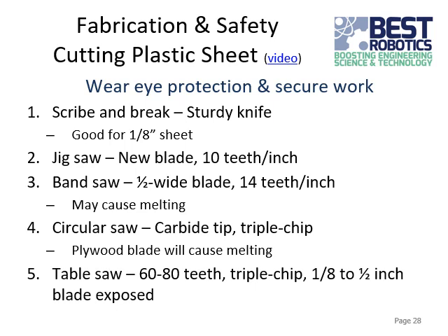Plastic especially can chip or melt and have little bits, like melty bits of plastic fly out while you're cutting it. And all that stuff is really bad, you don't want it in your eyes. So always wear eye protection when you're cutting things or working with power tools or anything like that. And then also make sure that you're securing your work. Don't try to cut something while it's loose and flopping around. Clamp it down to a sturdy surface, or put it in a vise or something to hold it steady.